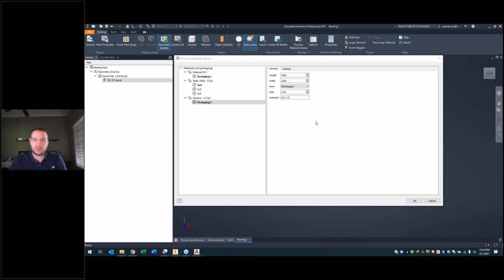The extruded, I'm going to say your D3 or whatever value you use for that first extrusion, doesn't necessarily have to be the dimension that it's using for the object itself. And that might be the actual dimension problem that I'm having with my part, why it's not going through, because it doesn't know what the actual dimensional thickness of that model is. And it's just a matter of going into your parameters and naming it. And I believe it's nest underscore thickness. I'd have to look it up. It's not one that I have memorized. But yeah, you can build custom parameters. But as far as iProperties are concerned, I'm not sure what iProperties you would need in the nesting environment.